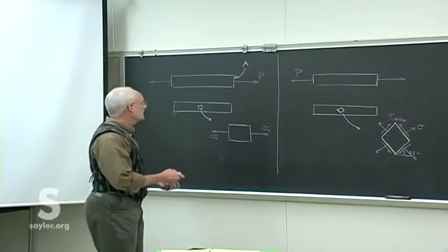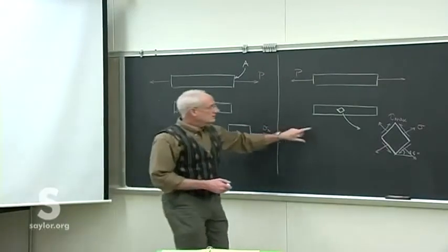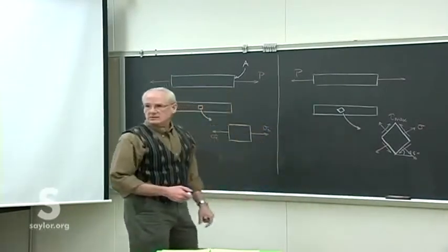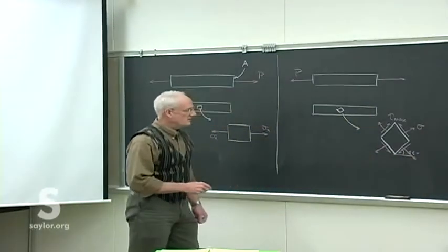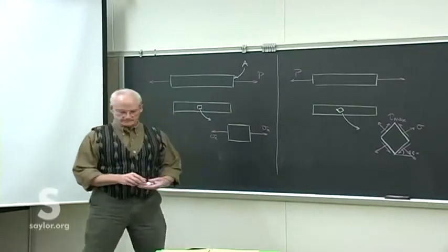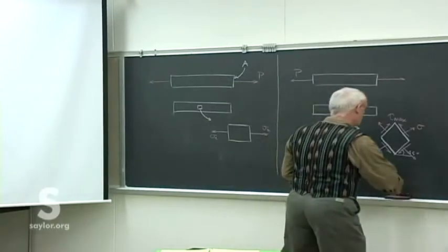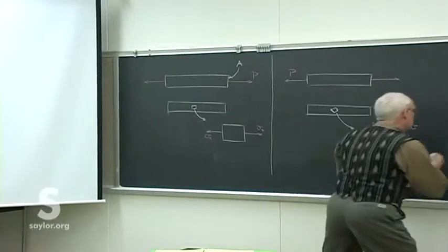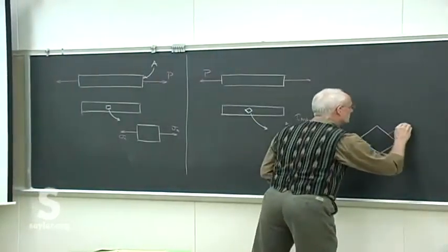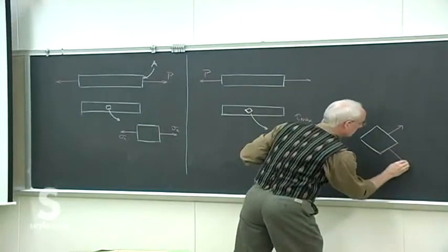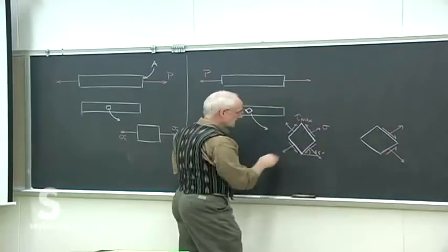So we've been able to combine our strictly orthogonal view with an oblique orthogonal view, where we know now from what we looked at earlier that things are at a maximum at 45 degrees. I'm sorry, if I think about it, I've actually happened to draw the shear stresses in the wrong direction for this tensile loading, because their components are going to be in that direction, not as I drew here.